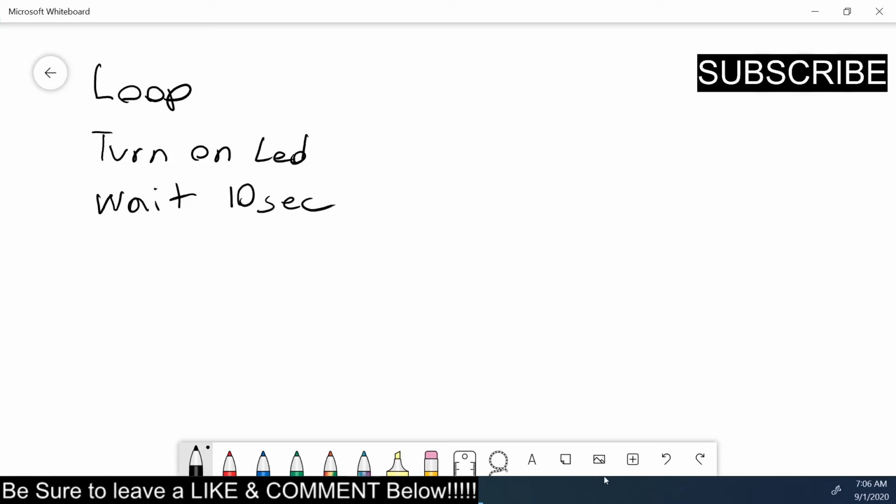Well, that 10 seconds is a variable that I can control with the potentiometer. So as I turn the potentiometer up and down, it'll go from, say, 1 second all the way to 10 seconds. But if I read the potentiometer up here, if I read pot here, it'll read it and then it'll do whatever delay I put in.